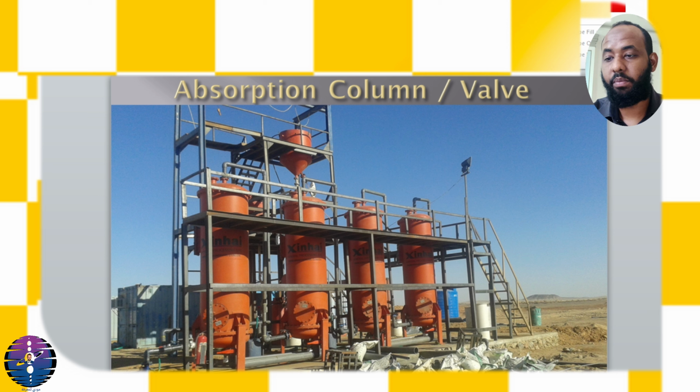The absorption process continues as the carbon in the first column absorbs the gold in the solution. Any remaining gold is absorbed by the second column, and this process continues until the carbon becomes fully saturated. We can determine when the carbon is saturated by taking samples from the exit flow.